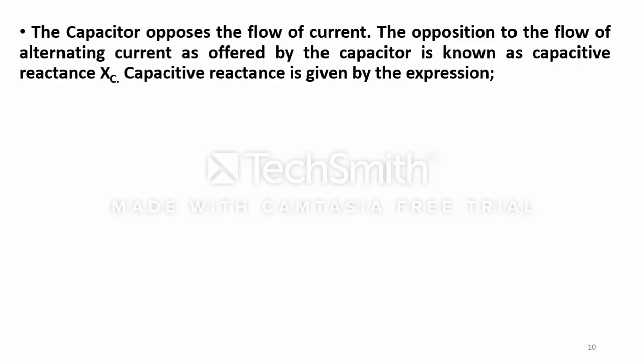So for capacitive reactance, we use the symbol Xc. Look at it here. Inductive reactance would be XL. Take note of that. And they have their expression. Look at equation 7. Xc equals 1 over 2 pi Fc. So the C there represents the value for the capacitor. Capacitance is measured in farads. F is frequency. Pi is a constant.